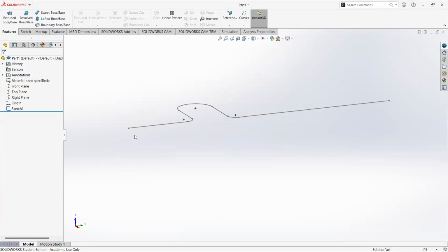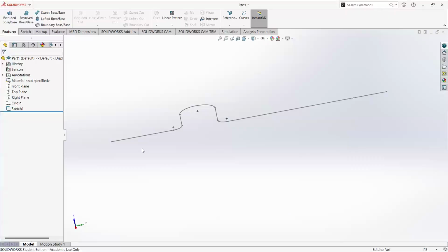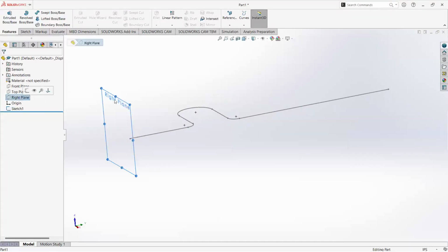Now I need to create a path that incorporates this path and the leg. And the leg should be straight down in the negative Z direction from here, right? If I keep my dimensions accurate. But I also have another problem where I'm too long because I drew at 0, 0. Actually, am I too long? Is that a true statement? It's not, because I started at 0, 0. My circle is going to come straight up at 0, 0. So that'll be fine. But I need to create a sketch straight down from here.